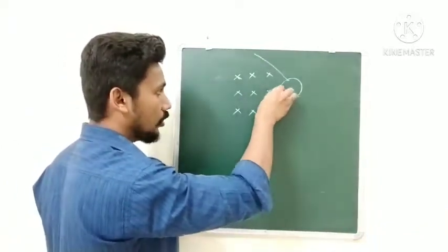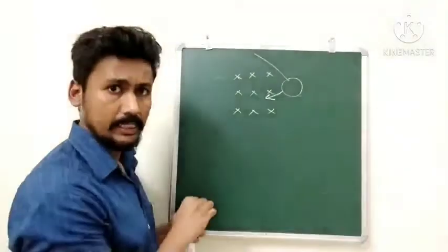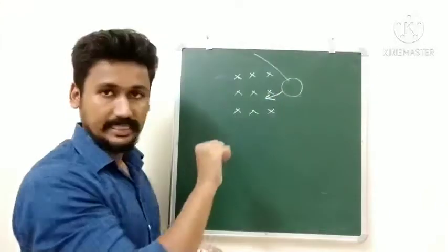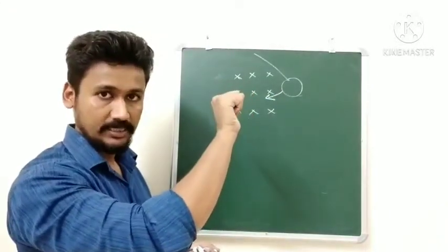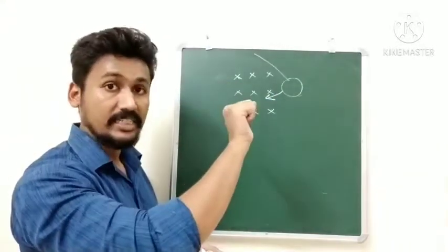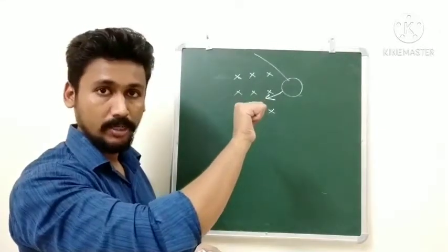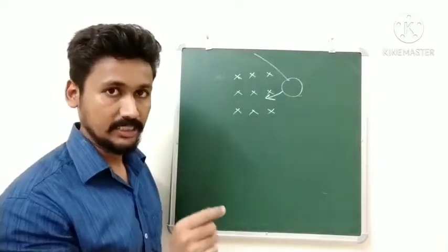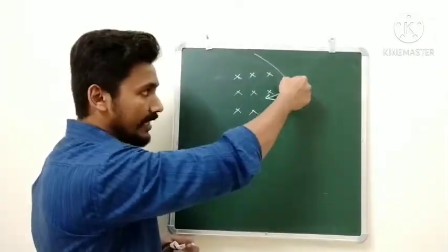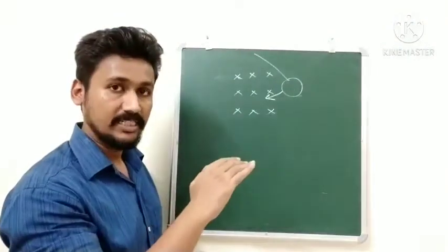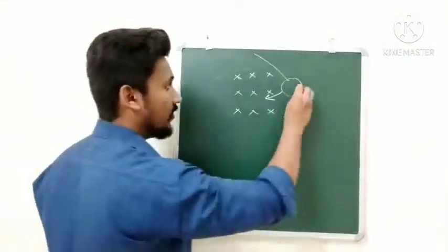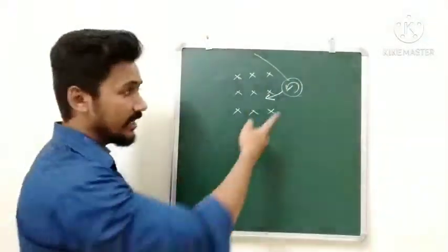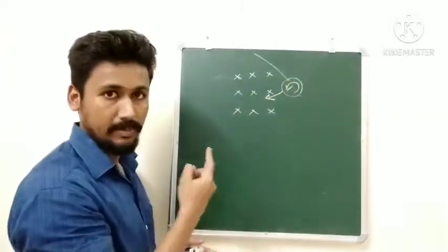So when this plate is going inside, we can now find out the direction of EMF. We know because it is going inside, the direction of EMF is like this. The direction of flux is like this. That is clockwise for me. So EMF will be anti-clockwise. That is given to us by Faraday's law and Lenz's law. So as the plate is going inside, the EMF that is generated will be anti-clockwise, and we will get an EMF like this. So we will get an anti-clockwise EMF in that metal plate.